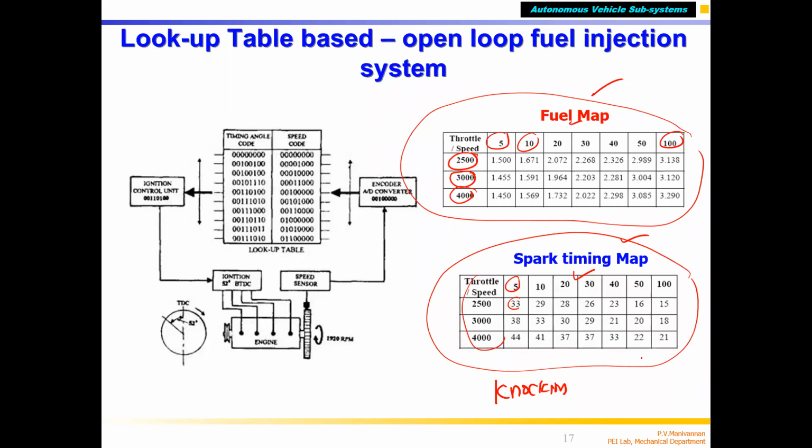The piston cannot move instantaneously because it has inertia, the flywheel, all those things. Because of that, the pressure wave, correct? If you have the cylinder in which you have the piston connected to the crankshaft, and all the fuel inside the combustion chamber burns instantaneously, correct? Instantaneous means zero. Nothing can happen in the universe in zero time, so it may be in the order of microseconds or milliseconds, a very short duration.